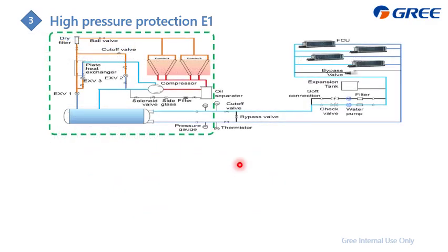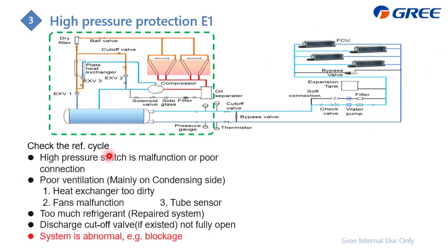And I put it on the cycles for better analysis. Also, the left side is the refrigerant cycle, the right side is the water cycle. And first we need to check the refrigerant cycle for the compressor startup within 15 minutes. And then the checking items are these.